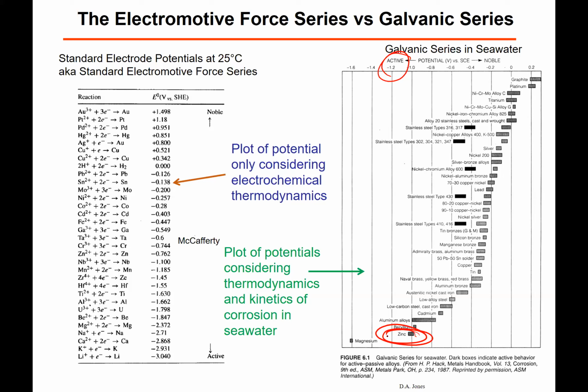And so what you'll see is these ships with these bars on the sides of the hull. Every 2 to 3 years, they just replace those bars. They do corrosion analysis to see how much mass was lost, and how active it has been. If it's been doing its job, then that material would be corroding. You're sacrificing some zinc versus the corrosion of your ship, okay?